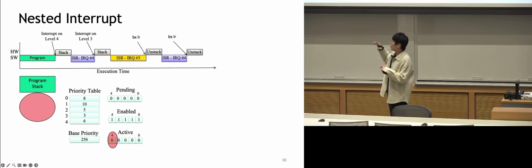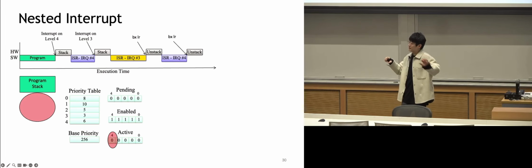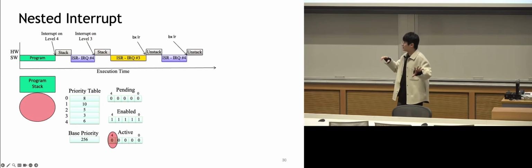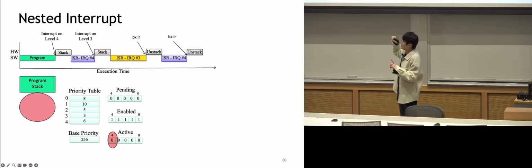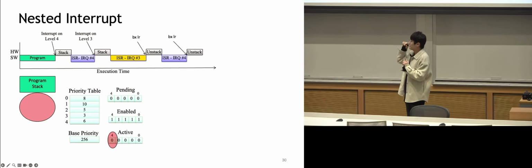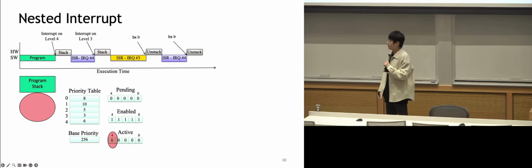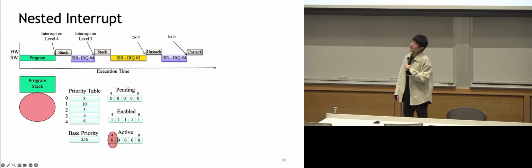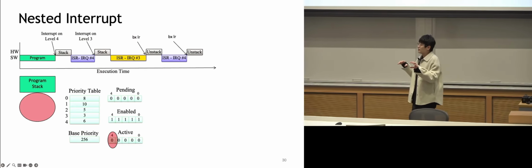But it is possible that while executing that same interrupt, there's another external trigger, meaning that same peripheral could raise another interrupt. So if there are 2 interrupt requests from the peripheral, and that happens while that interrupt is active, then it's possible that we have both of them on 1. So you have to have an interrupt that's executing, and then preemption happens. On that one, it won't be preemption because they have the same priority.